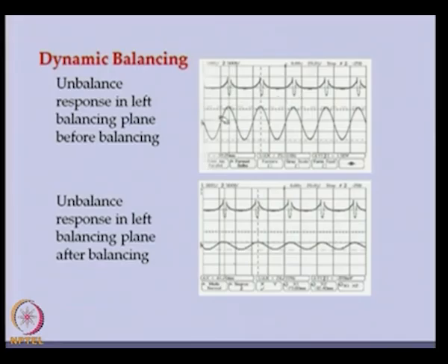So, it has been balanced by the procedure described earlier, and now you can see that after putting the correction mass, we again measured the displacement, and there is a drastic decrease in the amplitude of the vibration after balancing.